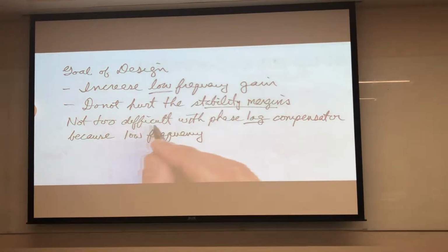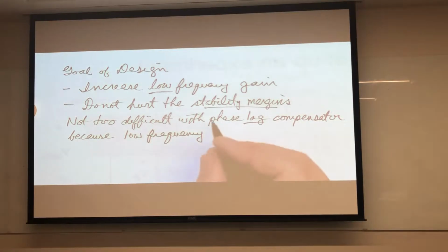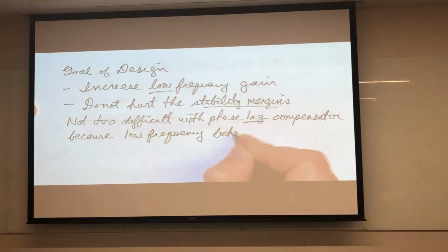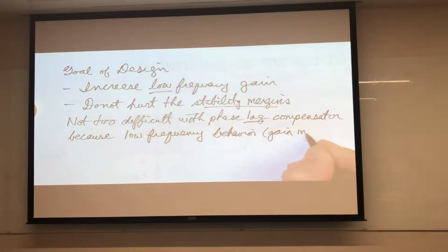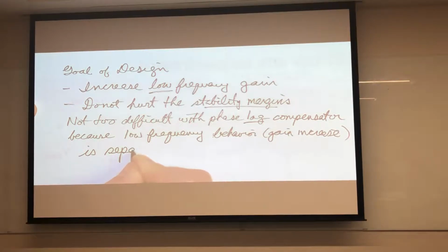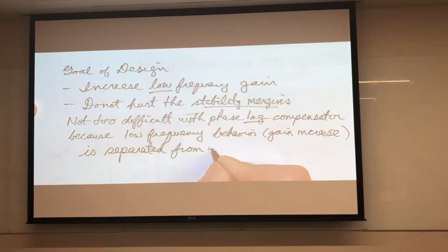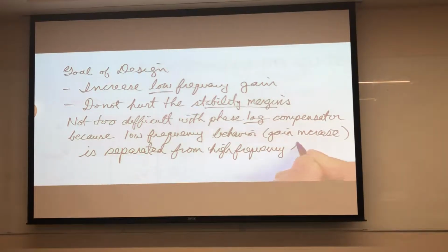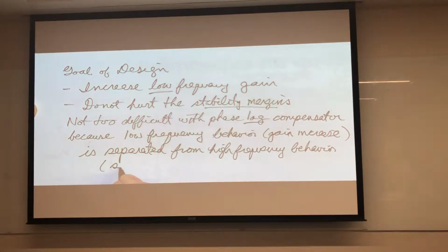So basically we're saying that it's not too difficult to achieve these goals with a phase lag compensator because the low frequency behavior, the gain increase that we want, is separated from the high frequency behavior. The high frequency behavior is the stability margin.